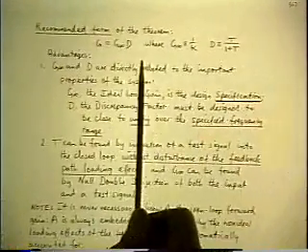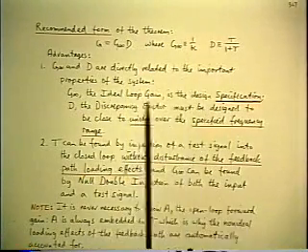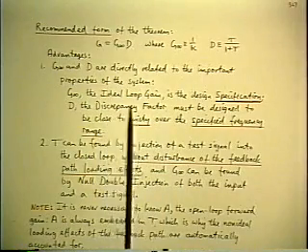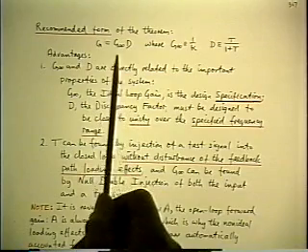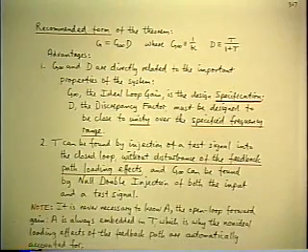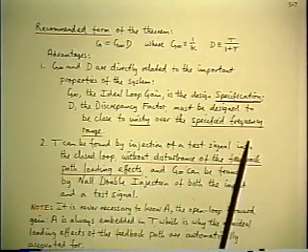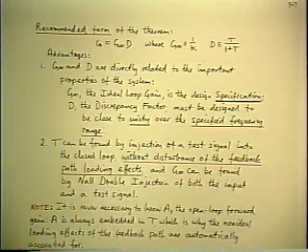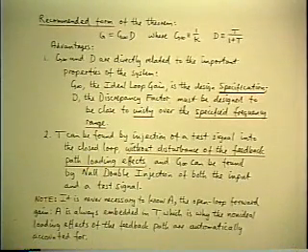So instead, redefine different parameters, G infinity and D, ignore the A, and we've just shown in the block diagram generalization how you can calculate G infinity and T and also F and D. Moreover, you can find all of those quantities without breaking the loop, but instead by injection of a test signal into the closed loop. And the bottom line is you never need to know what the A is. It's always buried inside the T.